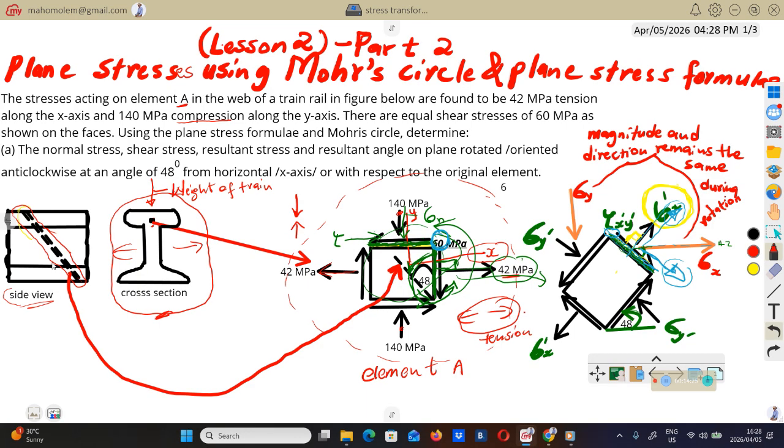Then after that, you can compare that maximum stress with the strength of the weld. So this weld is going to have a certain strength. So you will take the maximum stress or the major stress that you are going to calculate, I'm going to show you, and compare it with the strength of this weld so that you can determine if this weld will be able to withstand or carry the stress that will be created there.